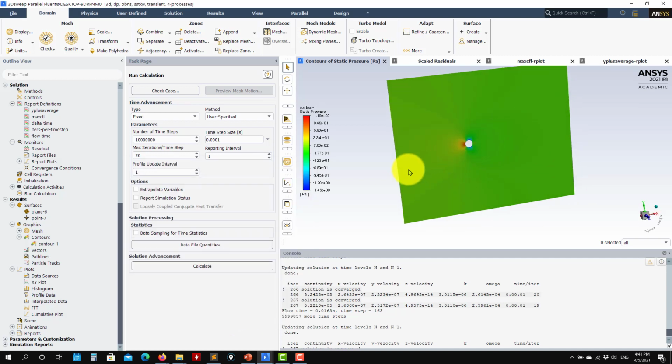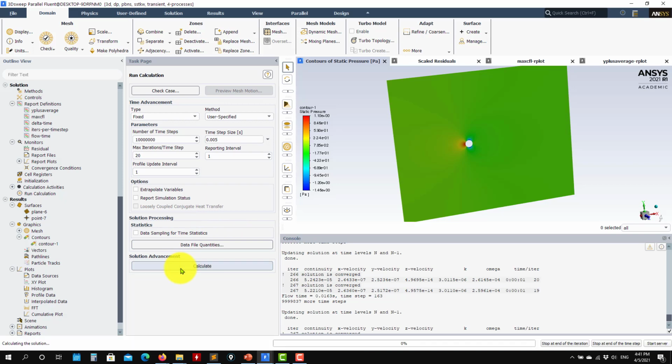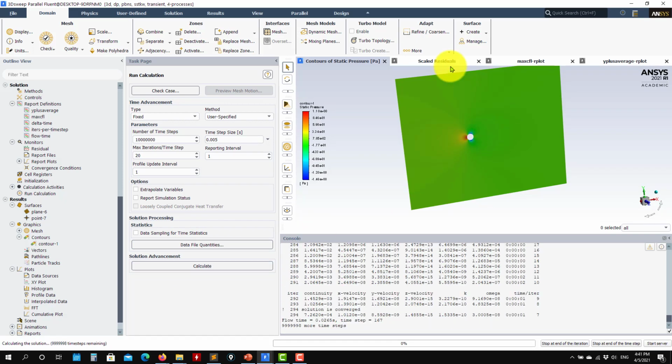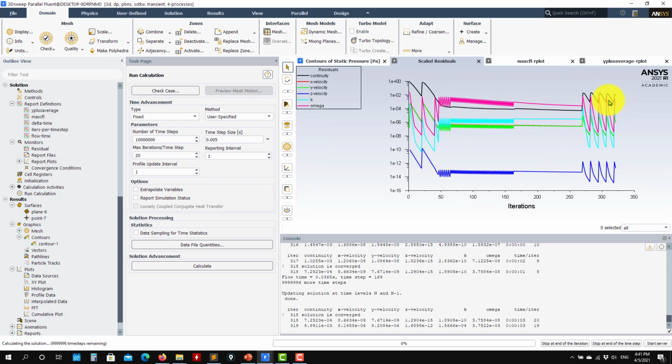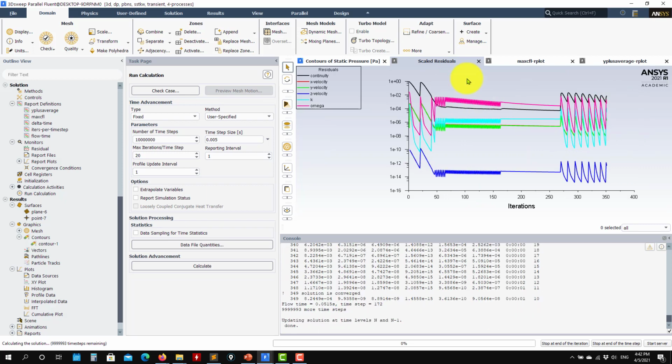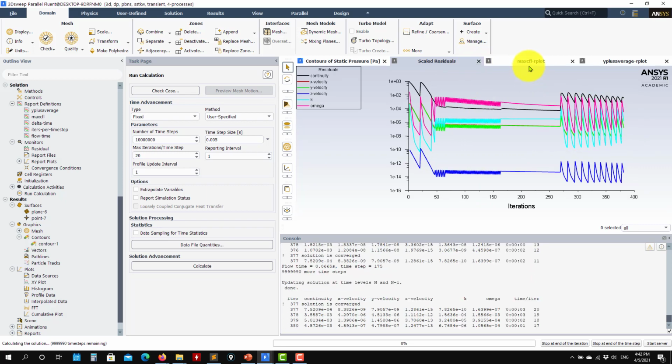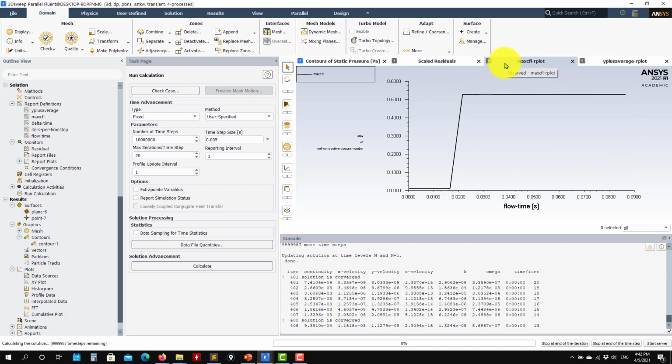So just to show you here, let's increase the CFL, the time step. So now I will put 0.5, okay? See that I stop it, and you can keep computing with no problem, okay? So it will start from the previous solution. So see that now you have a jump here in residuals, but don't pay attention to this, okay? This is not a direct indication. You need to monitor forces.